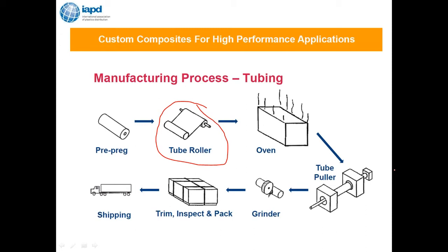You leave it in. After it comes out of the press, it goes to a machine called a tube puller, which mechanically yanks that mandrel out of the center, leaving you with a hole that goes through the middle of the rod, and voila, you've got a tube. Once again, the outside diameter is a little rough, so it's got to go through a centerless grinding process, at which point you've got your finished product, and again, make it into whatever that engineer has designed on the blueprint.